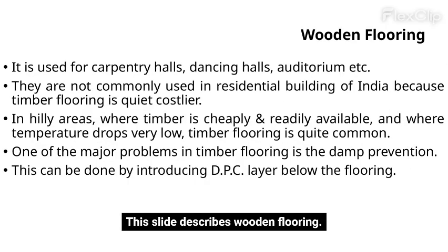This slide describes wooden flooring. It's used for carpentry halls, dancing halls, and auditoriums. It's not common in Indian residential buildings due to its cost. In hilly areas with readily available timber, it's more common. Damp prevention is a major concern, which can be addressed with a DPC layer.